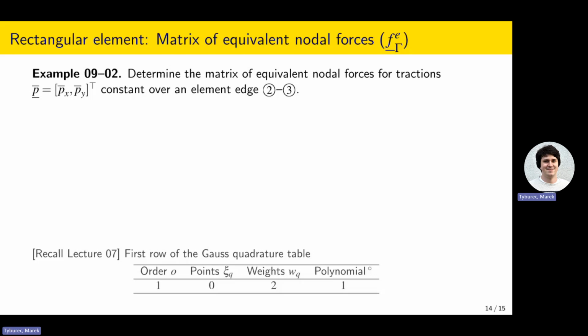And what is inside? Inside is the guy here. So that's this shape function matrix of the element. But now this is explicitly evaluated at x equal to Lx over 2, so this is fixed. And the second argument is y, because that is the integration domain. Okay. Again, I guess I forgot to transpose here. I'm very sorry.